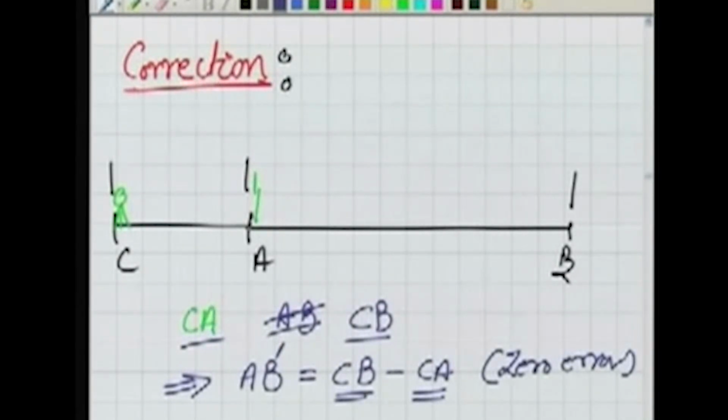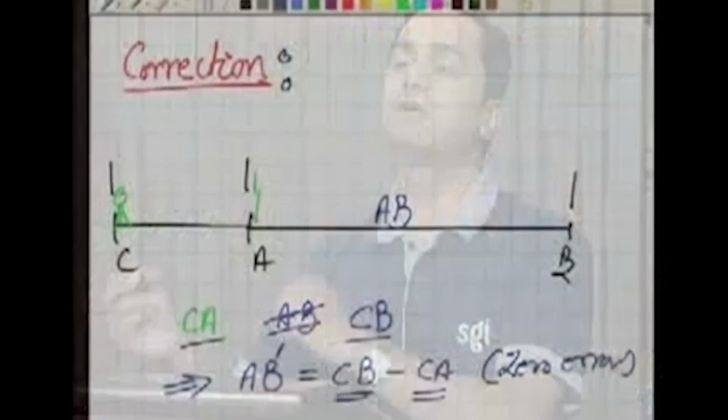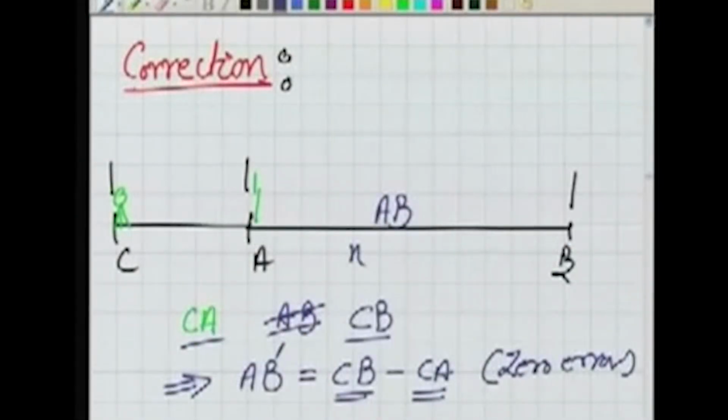This AB is also known from the measurement in the field, or again I am saying this is a standard length. These 2 points AB are on a standard. So we know exactly this value of AB, and this is generally equal to n times lambda by 2. We have taken these 2 points n times lambda by 2 far apart.